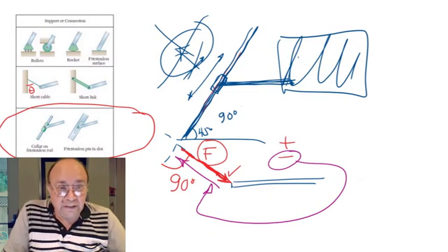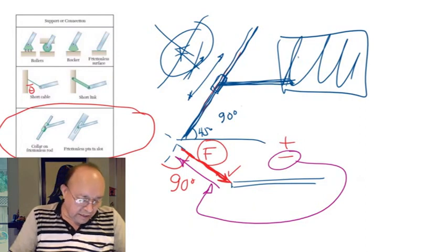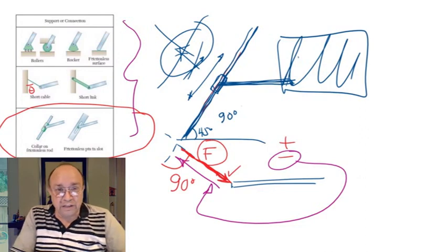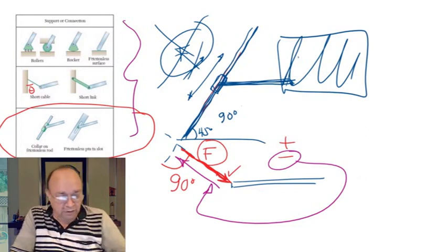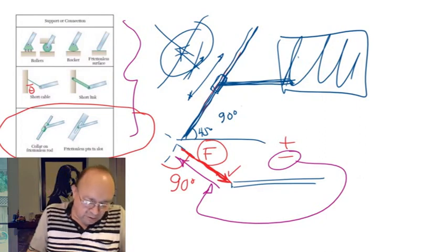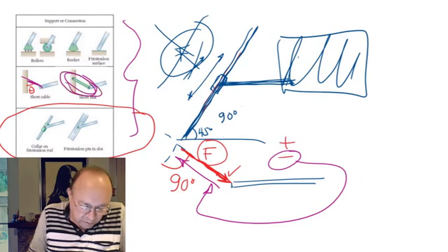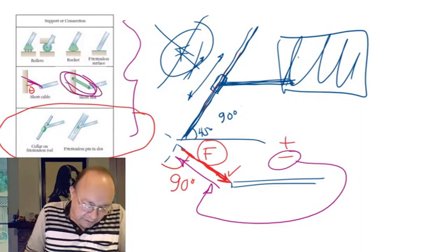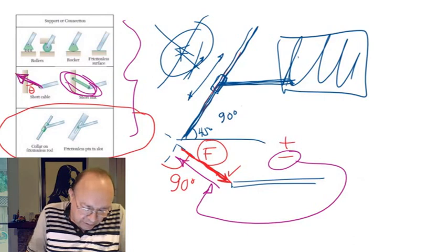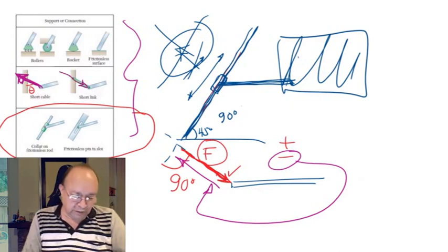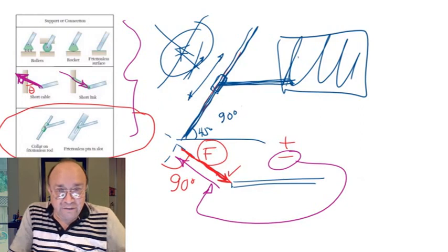So as we have said, in all these initial cases, you have a reaction that has a known direction, which depends on the geometry. What is the direction of the cable? Same here. I didn't discuss this one here. This one is similar to the cable, but the difference is that the cable can only apply tension, only going in that direction, away from the body. This one can apply tension or compression, so the force can be in this direction or can be also in this direction, right? But either way, that doesn't affect your calculations.